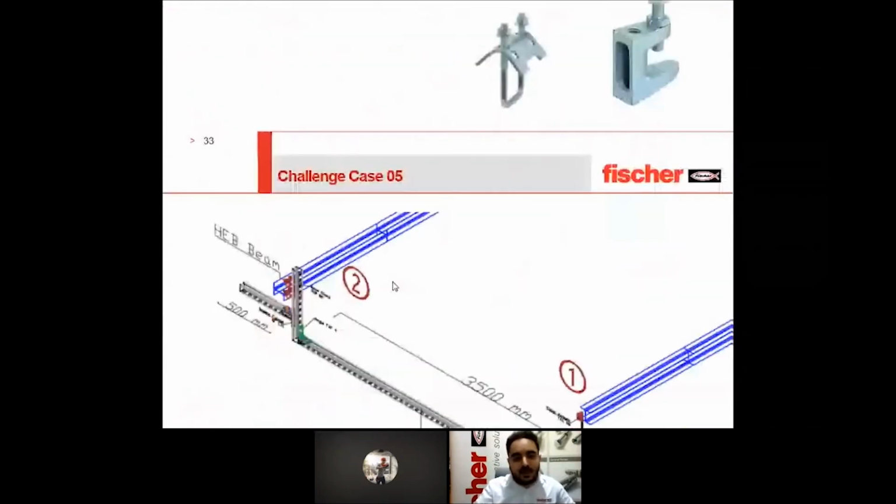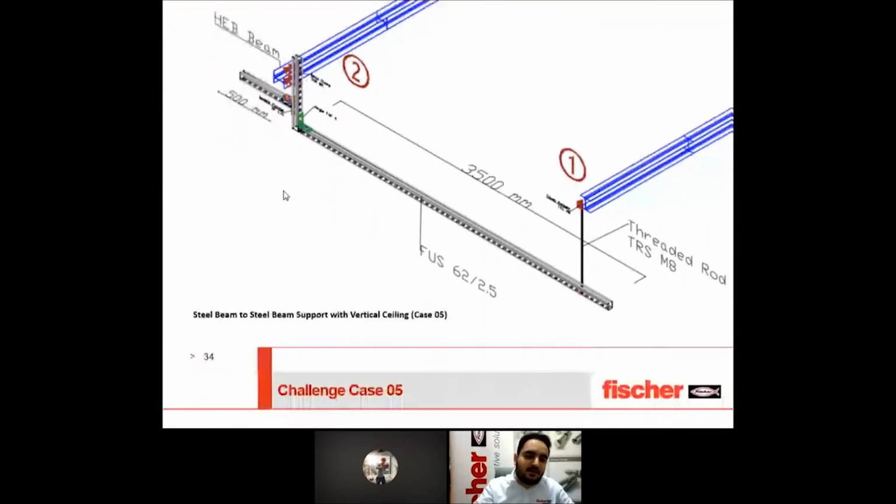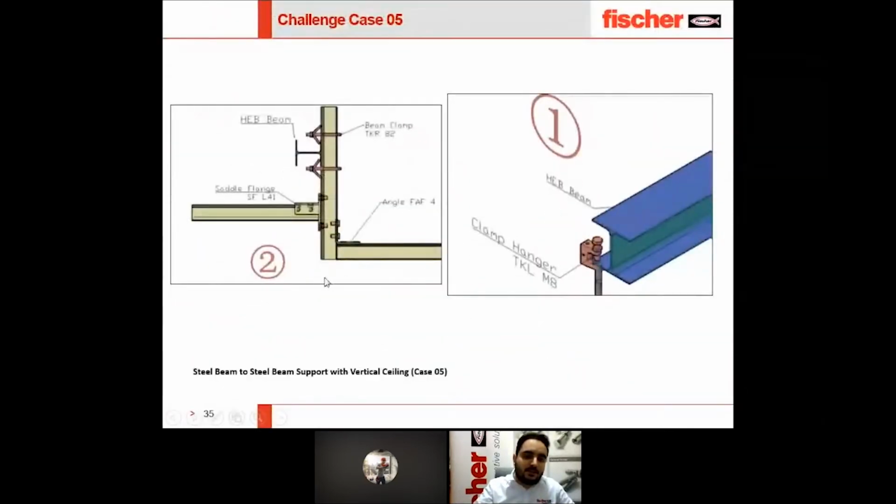with a small cantilever here, because we have a ceiling here, it's running here and comes a little up from here and continues in that direction. So we need to make some cantilever here to hold this part of the gypsum board.